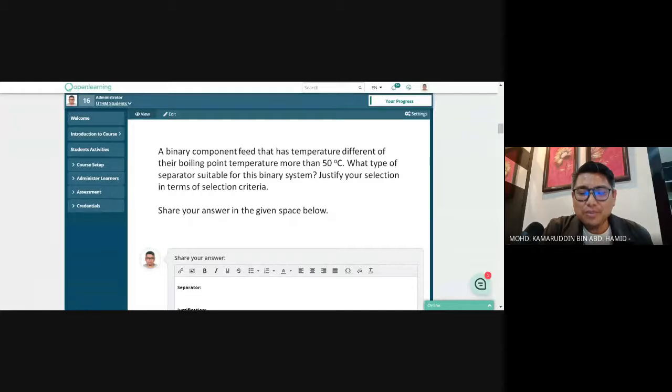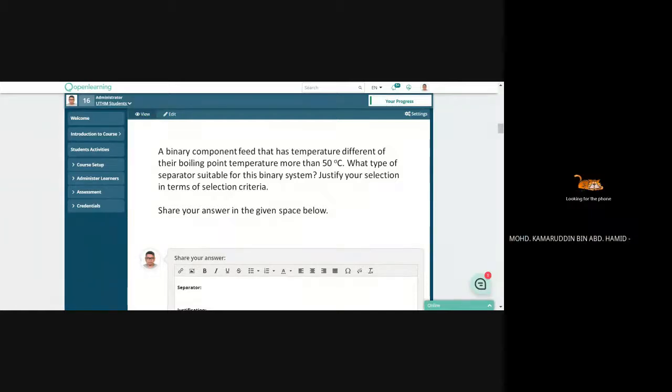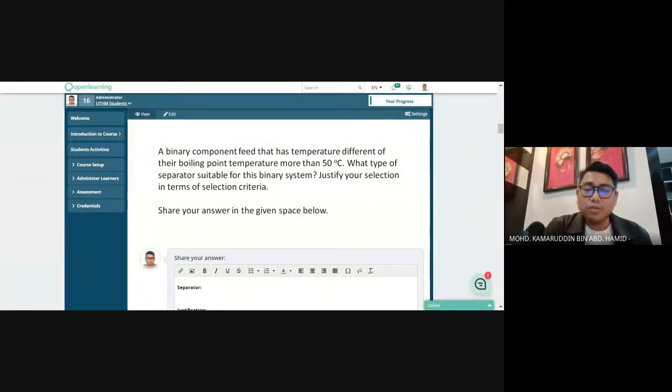One stage is equivalent to 0.5 meter. Half a meter, one stage. That is the standard. So if you have 200 stages, you have 100 meters. Imagine 100 meters, the distance you run, stood upright. It's very, very high. That's why if you have more than 200 stages, basically the design is not feasible. 100 meter height.